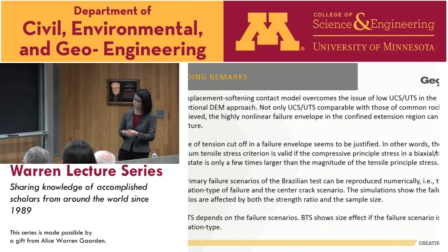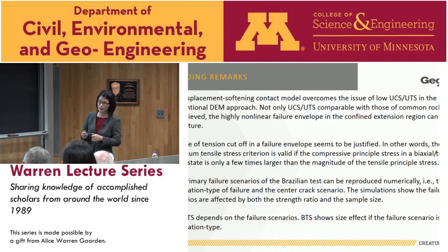And we show that the tensile strength from the Brazilian test depends on the failure mechanism and also the size, the diameter of the sample. And I would conclude it's rather dangerous to use that.